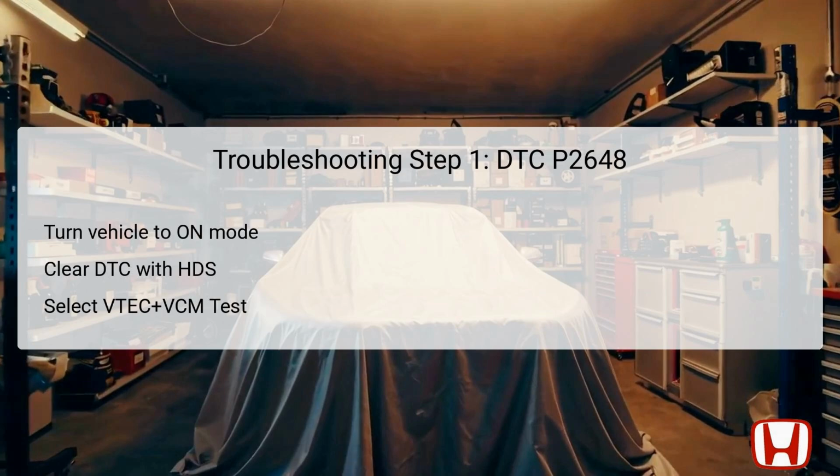Following this, the technician should select the VTEC plus VCM test in the inspection menu and proceed to Solenoid B within the Sol-V activation options. This specific selection enables the technician to activate a system that assesses the functionality of the solenoid. The outcome of this step will help discern if a DTC for the rocker arm oil control solenoid specifically appears again, indicating whether the failure can be duplicated or if it is an intermittent issue.